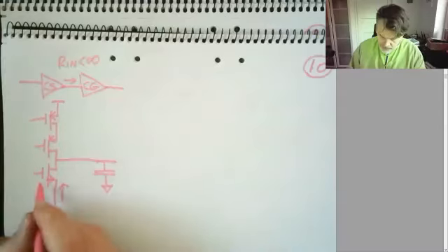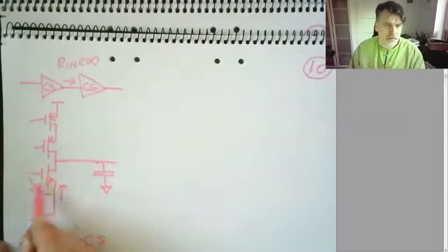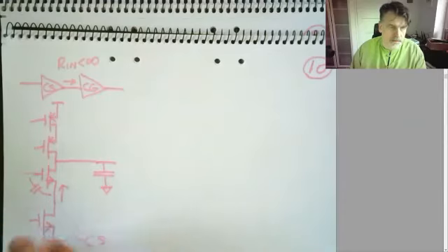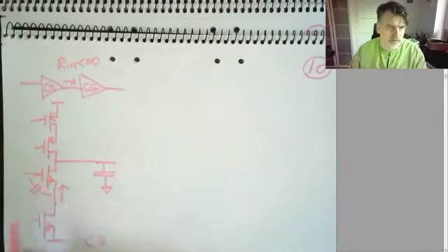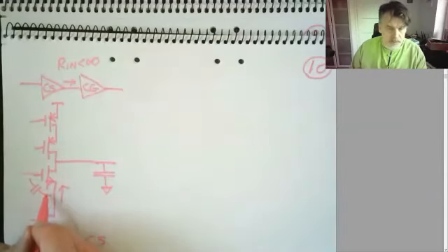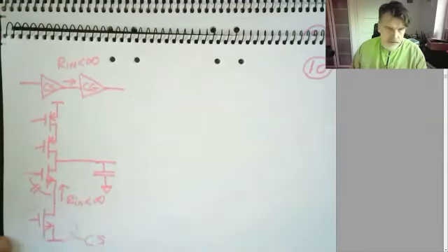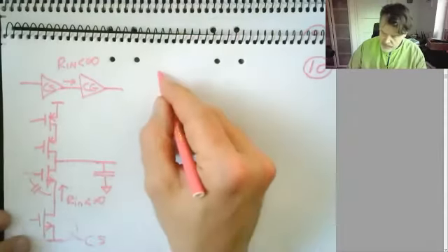Small signal wise, it still sees the same CGS of this transistor. If you remember, this is my common gate, and we had just flipped more or less the direction of the polarity of the driving signal compared to the common source. So the same thing for the capacitance, it doesn't change. Whatever capacitive load I see for a common source, I see the same type of capacitive load for a common gate. But I have an R in here which is less than infinite. Could still be large, but it's less than infinite.